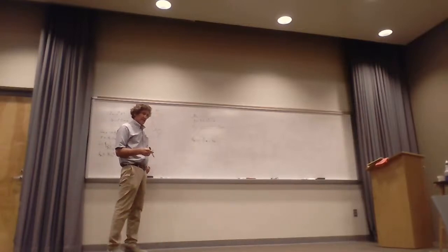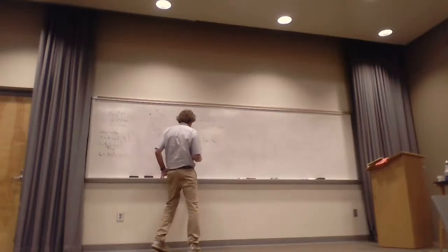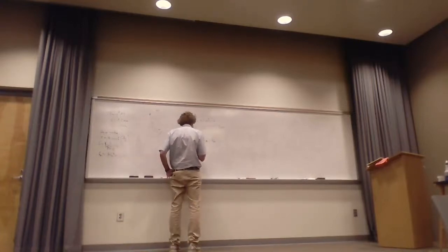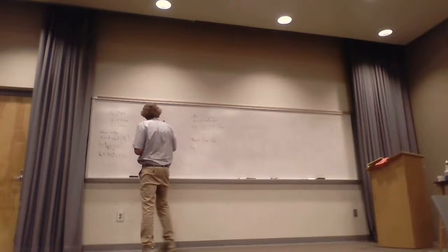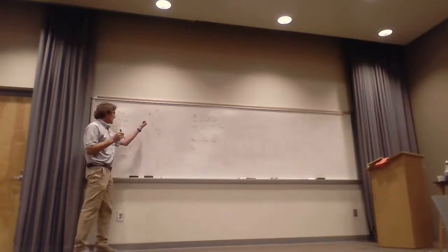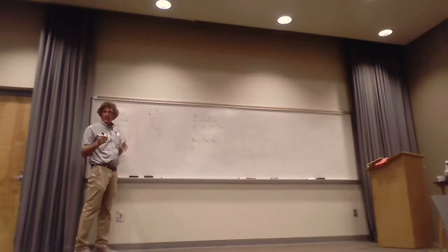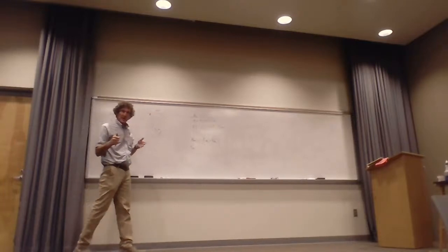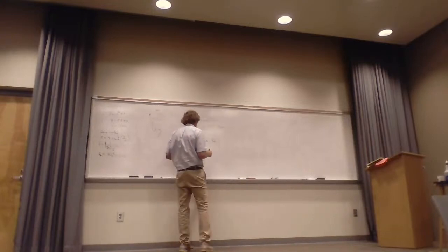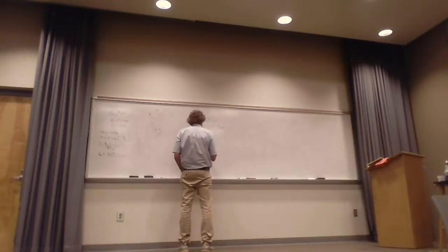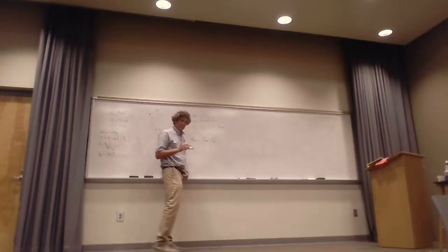We can say that R_AC, and the reason is current goes down one of these conductors, say the inner, and it returns on the outer. So the net resistance per meter is going to be the sum of the two. They're not in parallel. So the AC resistance, since it's per meter, the length is 1.